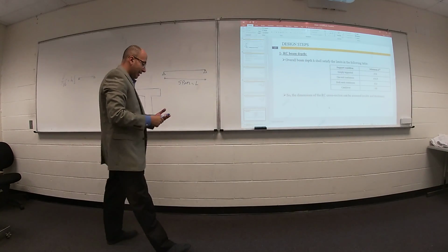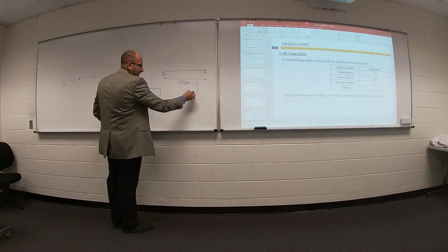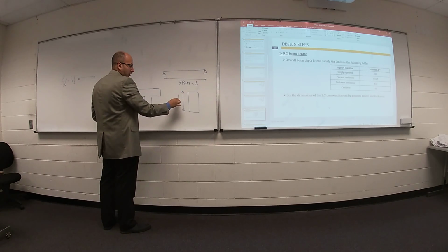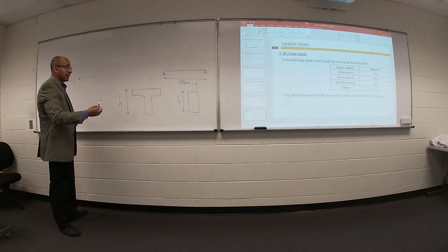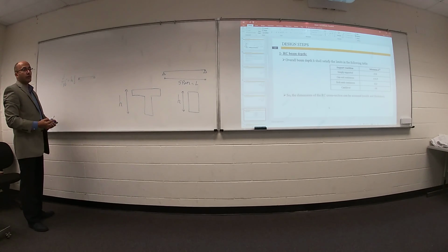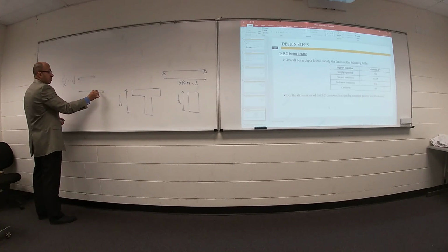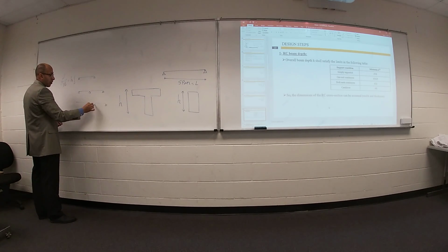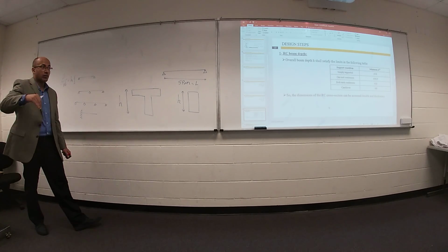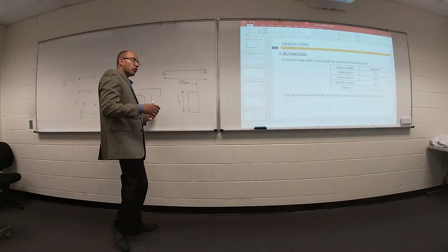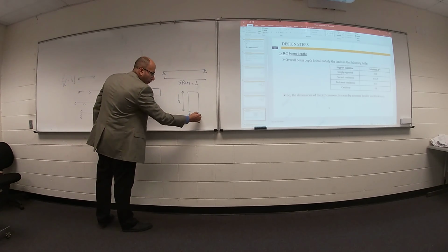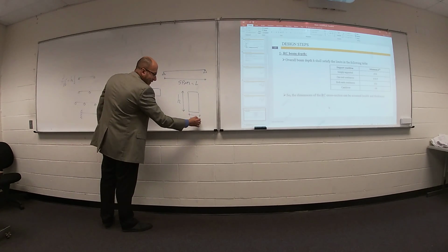This table can tell you, if your cross section is a rectangular cross section, what the total depth H is. If your cross section is a T section, what is the total depth? It is based on the type of your beam: simply supported, or continuous from one side, or continuous from both sides, or cantilever. Today, your cross section is a T section. That's fine. Your width here, do you remember how much? 12 to 15 to 16 inch. That's fine.